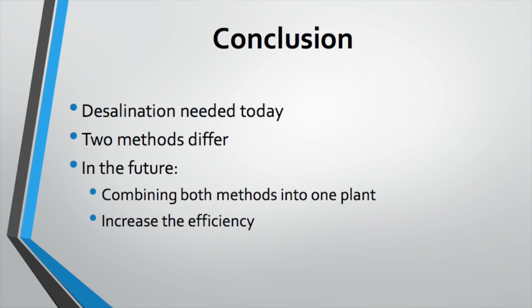The location of multi-stage flash plants are predominantly in places where the feedwater source is the ocean, while reverse osmosis plants can also use the ocean for feed. Instead, they are generally used for brackish water sources that have a lower starting dissolved solid concentration. Considering the efficiency of each source, multi-stage flash distillation outputs a more pure stream of water than reverse osmosis, but the energy needed to vaporize the water in multi-stage flash distillation surpasses the energy needed to overcome the osmotic pressure in reverse osmosis. Translating into cost, reverse osmosis is generally cheaper than multi-stage flash distillation due to the need for a heat source.